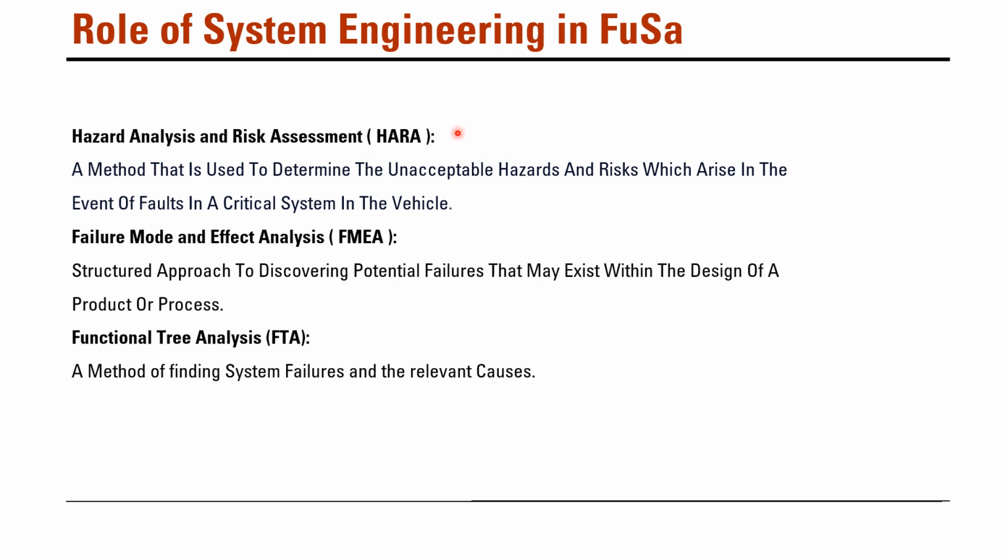So in the HARA stage, we do more study on the concepts and we define items out of the concepts to be implemented, and then we perform risk analysis of these hazards, and then we rate these hazards with different ASIL ratings.